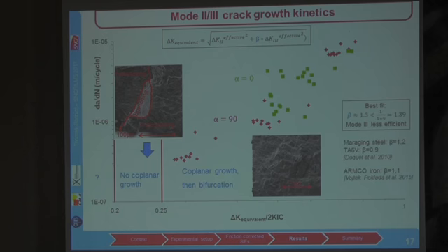And this beta is consistent with the beta equal 1.2 found by Doquet et al. for maraging steel, and the beta equal 1.1 found by Wojtek, Okuda et al. for Armco iron, although the loading range was very different in this case. So the growth rates are between 0.1 micron per cycle up to 10 micron per cycle, so we are in really high growth rates.